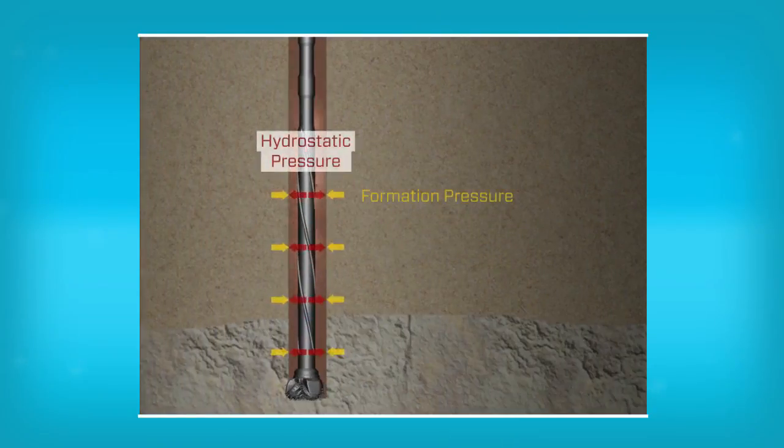The most important use of drilling mud is maintaining the primary well control. The hydrostatic pressure exerted by the column of fluid in the wellbore prevents gas or fluids from entering the well, where it could pose a hazard both inside the well and at the surface. This is achieved by carefully measuring and adjusting the density of the fluid.